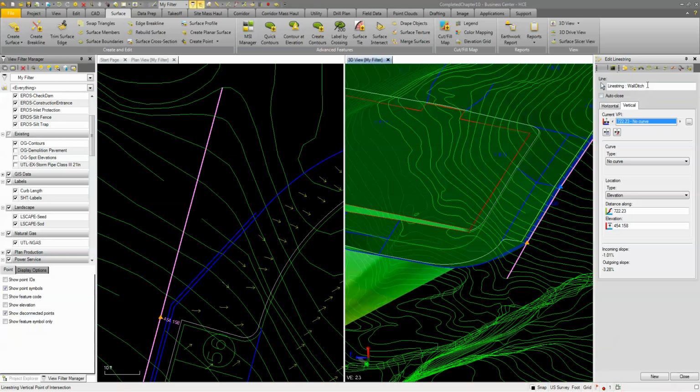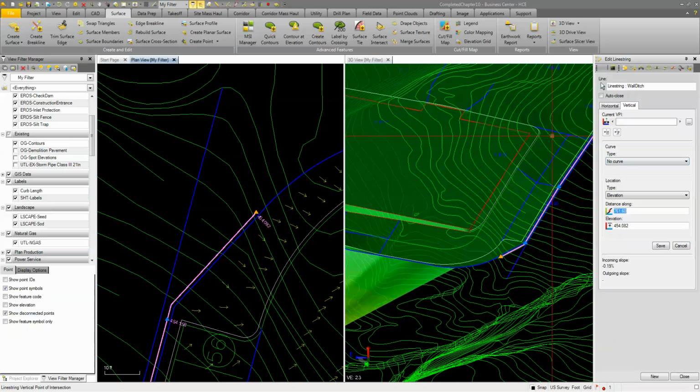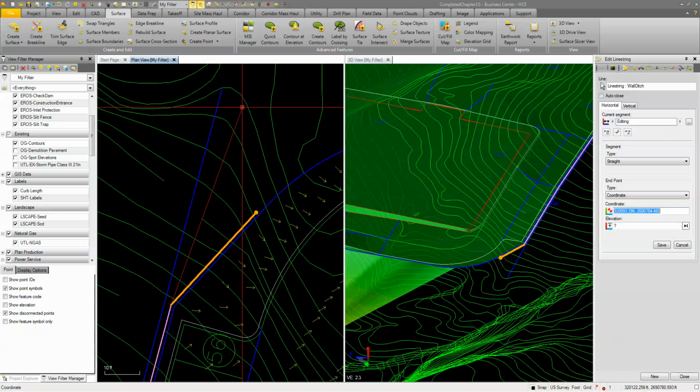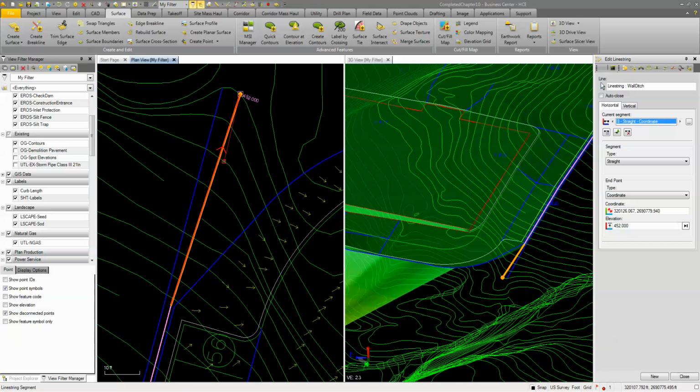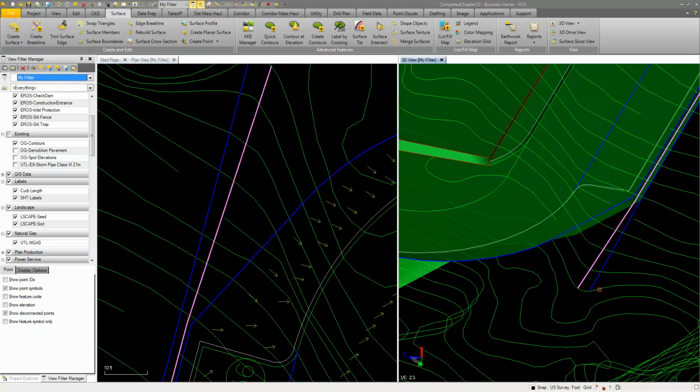So now what we'll do is we'll switch over to the other line. Again, we're going to left click to select that point where we will remove it, and then switch over to horizontal, and we'll move this and we'll just bring this down here, and we'll widen our ditch at the end a little bit so that we've got some spill out. Alright, so now I've just edited those. So now that I have that, I've got my slope going out, I got my ditch going out.